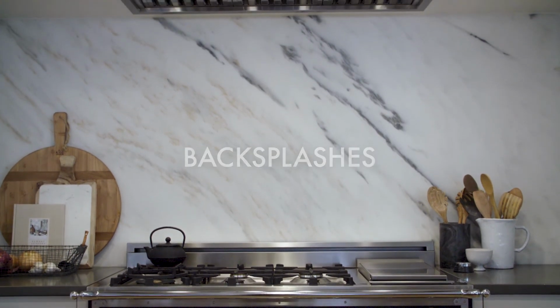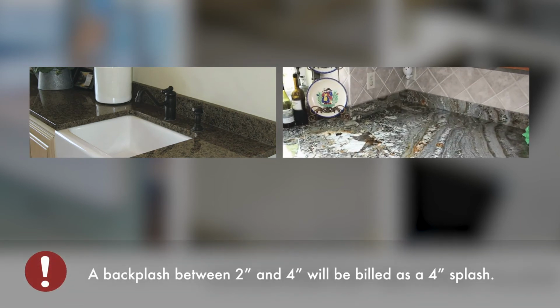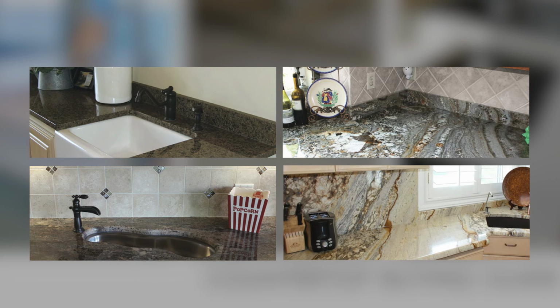Backsplash. The most common stone backsplash is 4 inches, as it provides the best water seal where the counter meets the wall. Another good option for good water seal is to cover the wall with tile above the stone backsplash. Some choose to use only tile as a backsplash. Be aware that over time the grout seal may deteriorate as building materials expand and contract. Finally, full-height slab material is an option. This means you are using slab material from the countertop to the bottom of the upper cabinets, or approximately 18 inches high, depending on cabinet design.